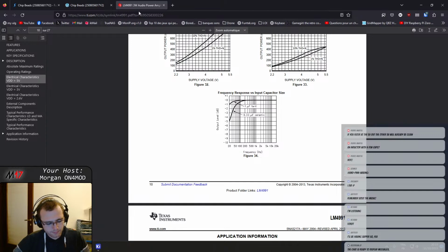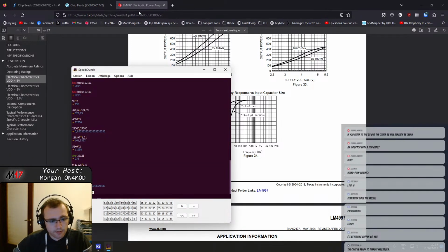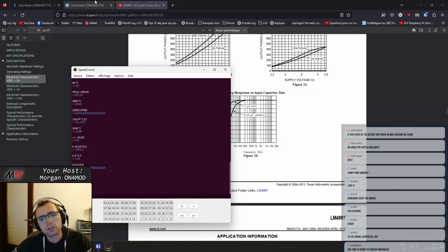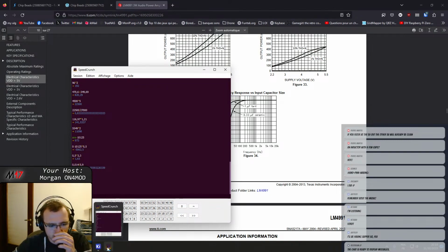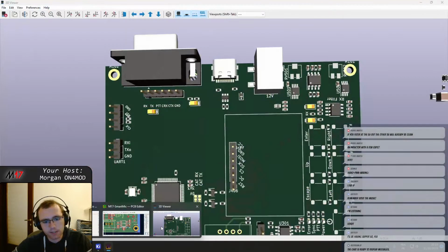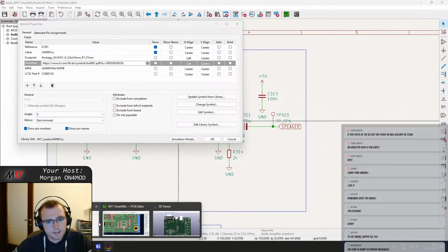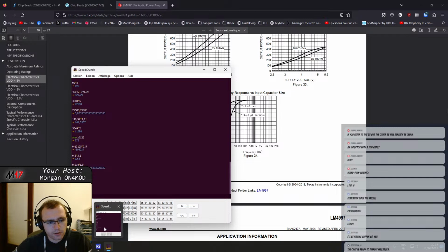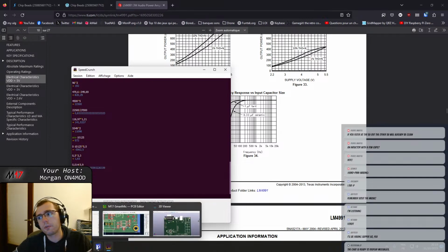So that means we have 0.75 watts with an efficiency of 60%, which is 1.25 on the inputs, which means we have less than 300 milliamps. It's not much actually, so we can clearly do LC filtering at some point right after the 5 volt outputs. Which cutoff frequency though? I don't know.